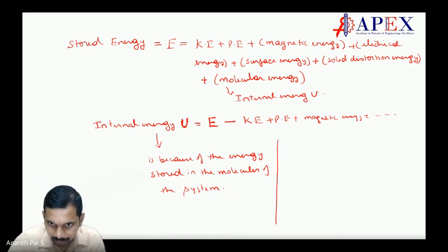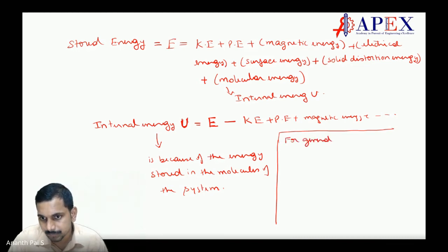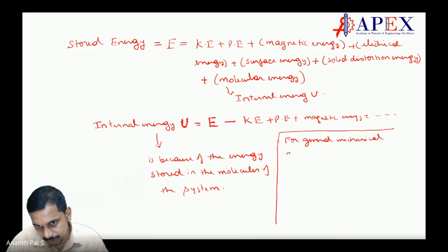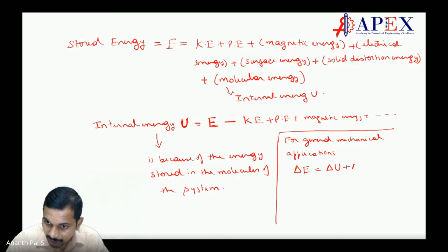So now I can say, for general mechanical applications, if I consider all the other energies are not there, the change in the stored energy is equal to the change in the internal energy plus the change in the kinetic energy plus the change in the potential energy.